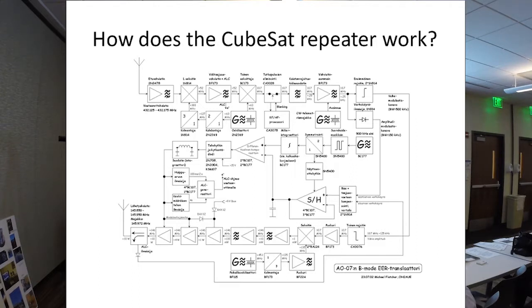As you'll notice the arrows here, as we're talking to this in the UHF range, 432.135 to 432.175, that's right, the new receivers and transmitters compensate for Doppler shift. So you can stay on one frequency. As this comes in, it's processed and it goes to the output side, which is going out on VHF 145.85.